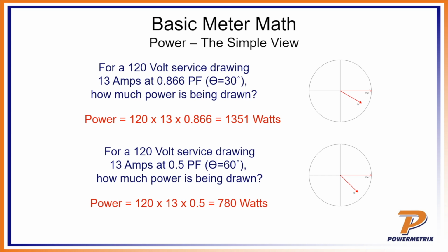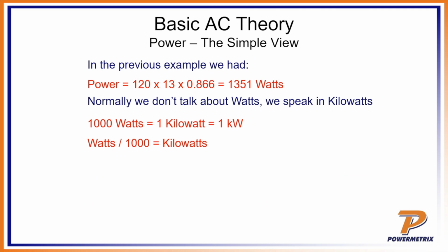So that tells me if I can test that meter, and this is a little sidebar, if we can test that meter at a horrible power factor, then we know that the meter should be good to go. So that's why we use such a bad one on that power factor test. Remember, we do a full load, a power factor, and a light load test, and we use that 0.5 on that.